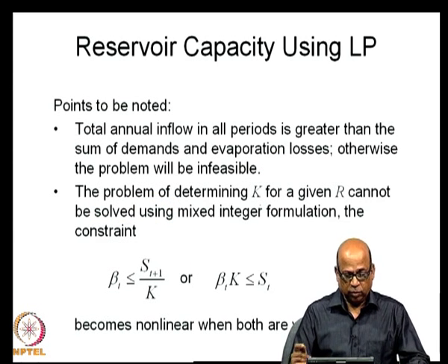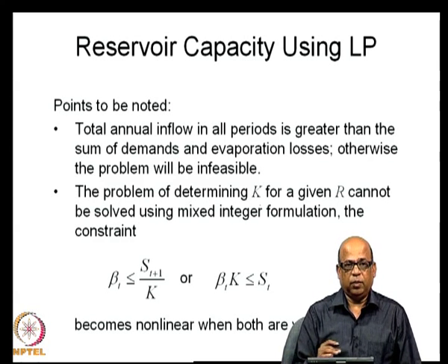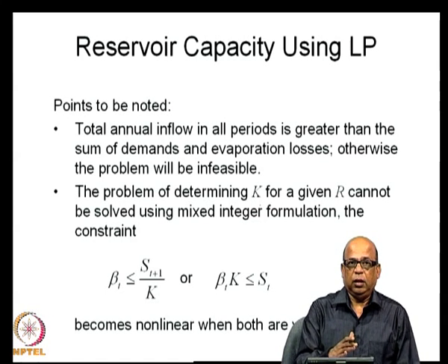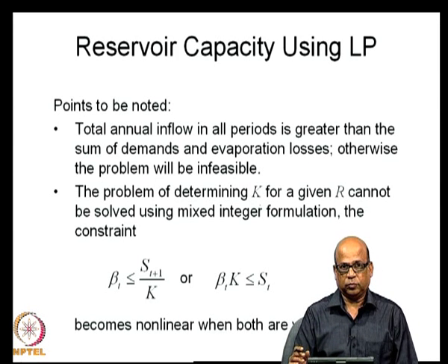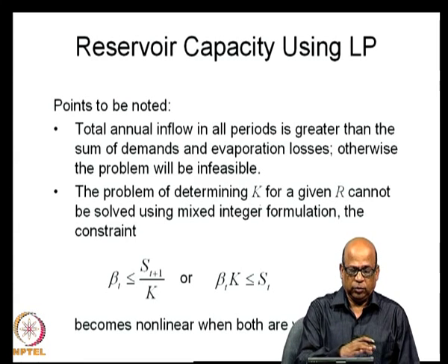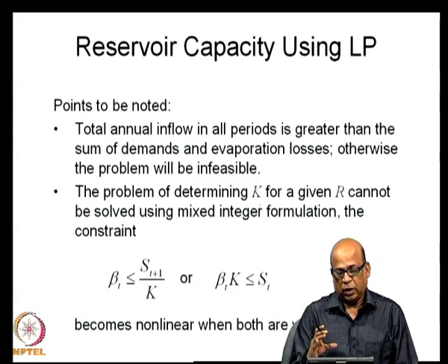Let us do this example now, but when we are doing this, let us recapitulate what we have done. In these formulations, when we are talking about storage yield functions, you remember these kinds of formulations, they will lead to infeasibility if your total inflow over all the time periods is less than or equal to the total demand plus the evaporation. So, that is the first check that you need to make.